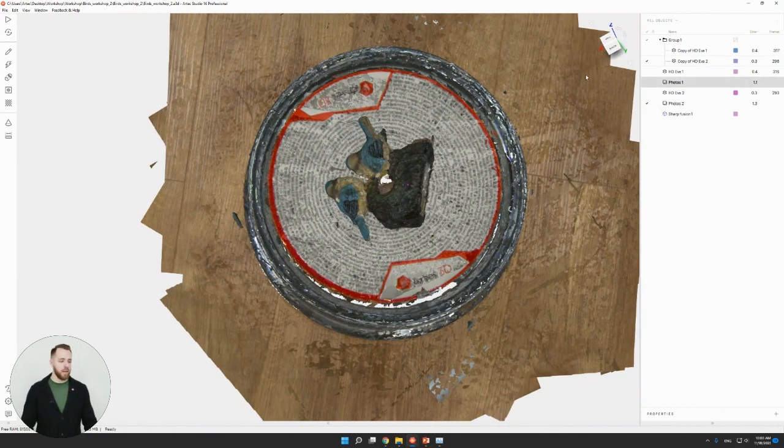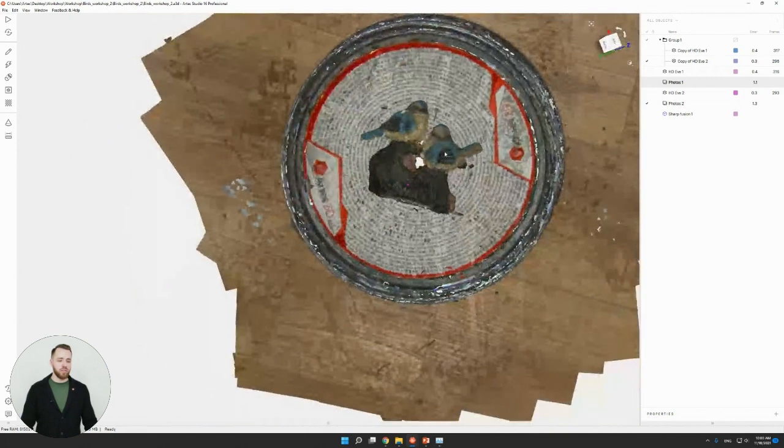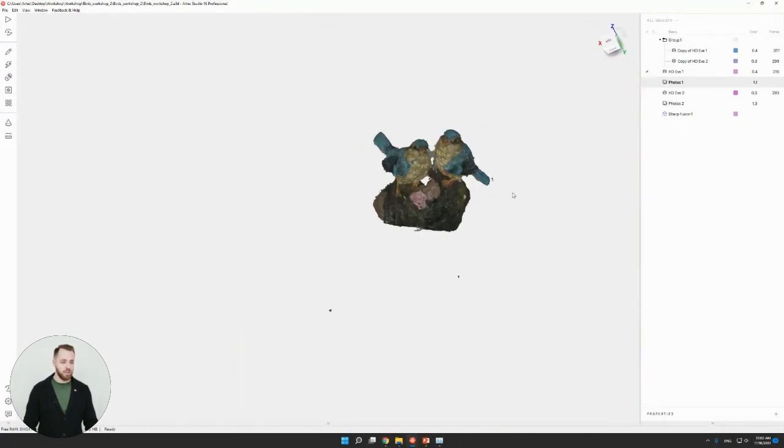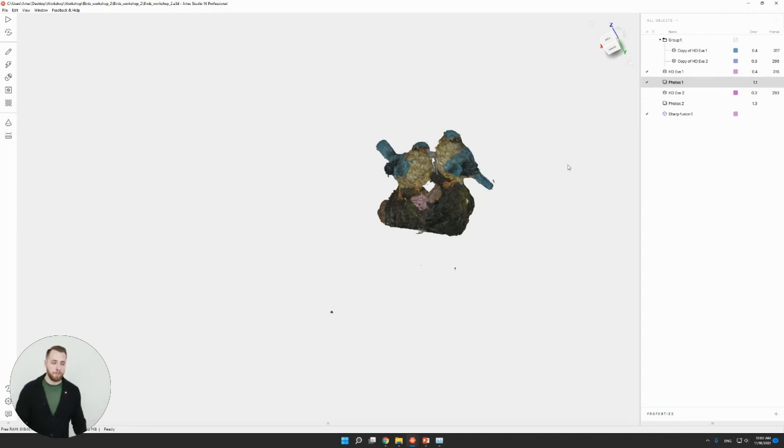So when I go about registration, what I do is first I process the project as is up until the fusion stage. I get my fusion, that fusion is simplified, and then I select the first scan, and here I've got the processed scan, the first scan. I select the fusion as well, and I select the first element, first photo folder.